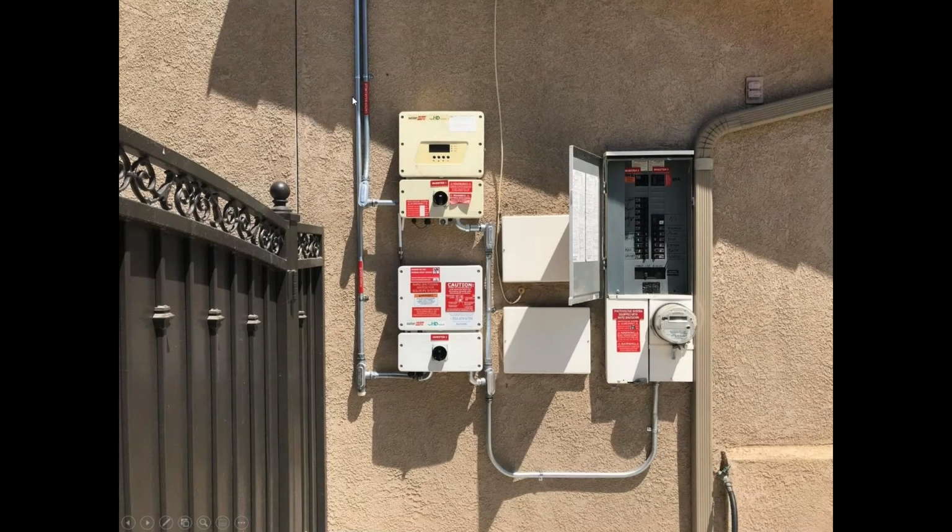And here's a picture of the AC side of things. This is 2 inverters. And actually this permit they were adding a second system. That's why the inverter on top is a little bit yellowed from the sun. That was existing. They came through, wanted a greater supply from their system. So they installed more modules on the roof and installed the inverter on the bottom. That's a second inverter. And both of those are interconnected through the existing service panel.